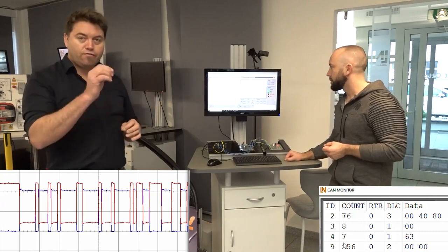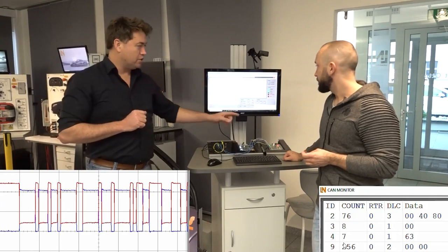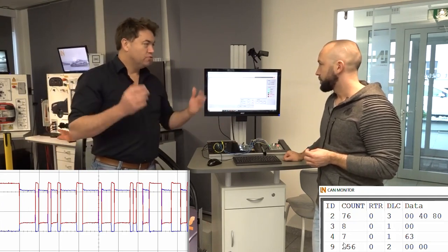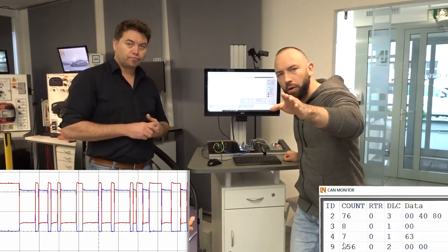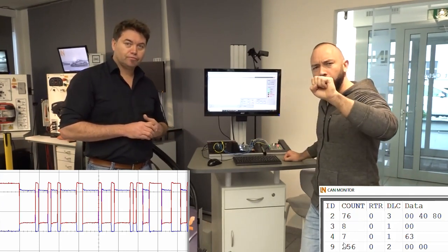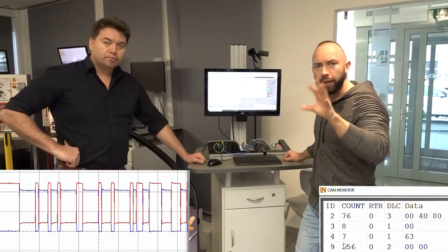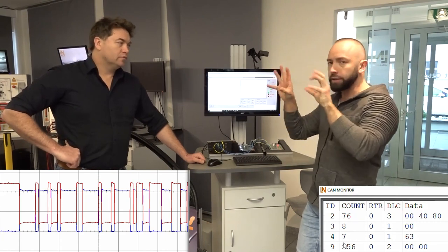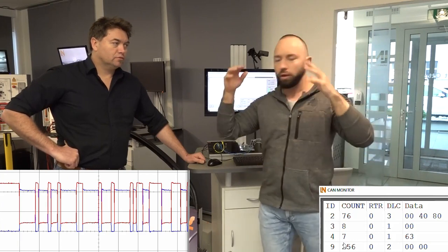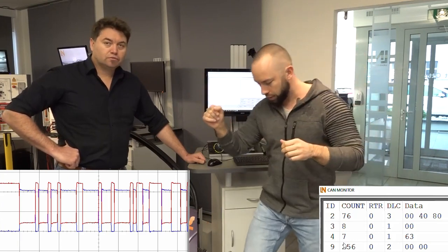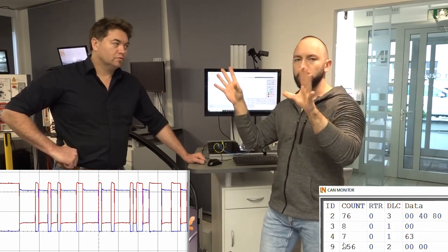So for every single setting of the brightness of a lamp, there is its own CAN bus signal we're seeing here. C, 2C, and that's so fantastic about it. So just remember, maybe you have seen that when a car in front of you goes on an emergency brake, suddenly the stop lights or the brake light starts to flash. This is realized through CAN bus. If you have a classical car, like an old Golf or whatever, there you just push the brake. This is setting a physical connection, lights go on, nothing more.